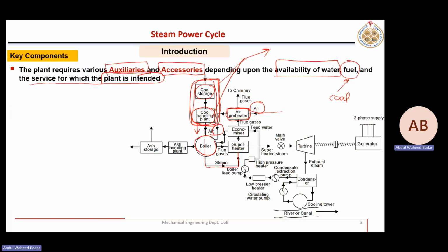Boiler, we use the term where the water is evaporating. Only that part is actually called boiler. But normally we use the term boiler, including superheater. Superheating is not a pure boiling phenomenon. Boiling is only inside the dome. Before and after, it's actually not boiling. That single phase region. That's why here those regions have been separated.